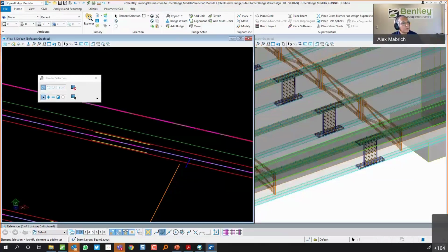Okay, so there is a question here for a deck replacement project. Do you recommend going with beam workflow or a standalone workflow? Existing substructure and existing beams need to be checked for the new deck. Again, it's up to you as a preference. I like to keep consistency in the design. I would like to use the beam workflow, right? Because then I have established the connection between physical and analytical. I don't need to worry about it because I know that my model rules, basically, right? So that is the recommendation.